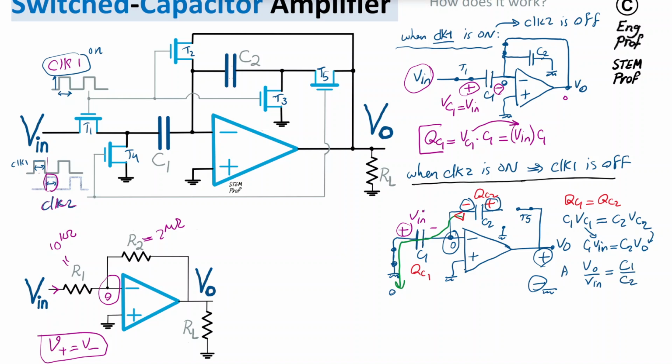This is the voltage gain of this switched capacitor circuit at the moment we apply clock 2 after the application of clock 1, as discussed in this example. This is the moment we look at the output. Again, we have to look at the output periodically at specific moments. We can only look at the output at those periods or moments. Otherwise, the output is invalid. That's basically we are sampling the output in this circuit.